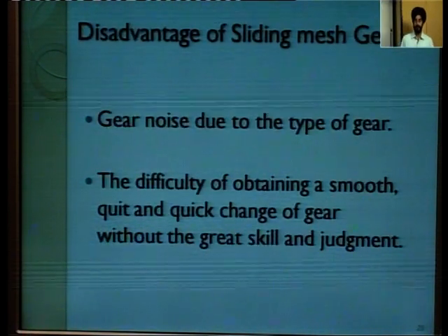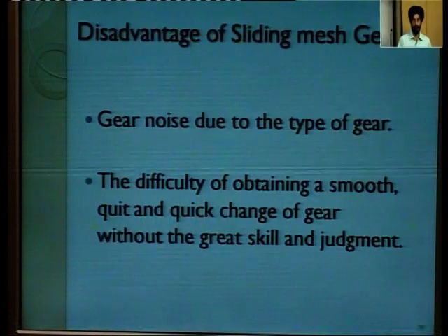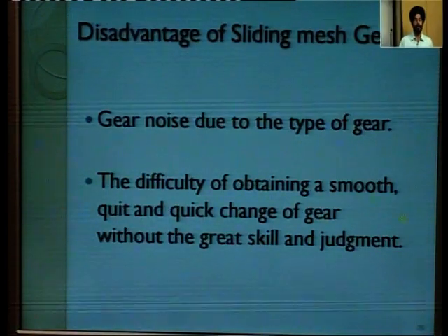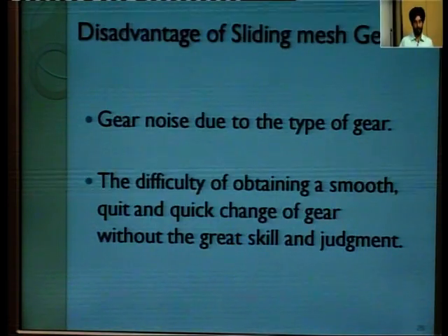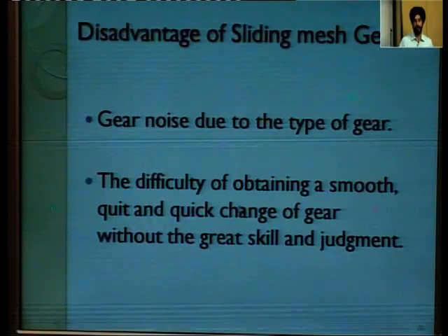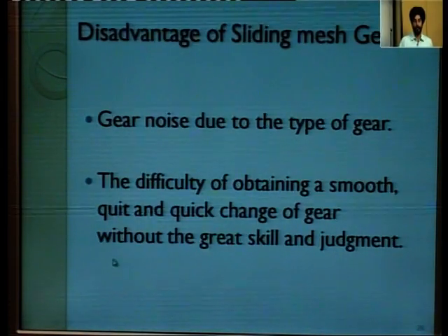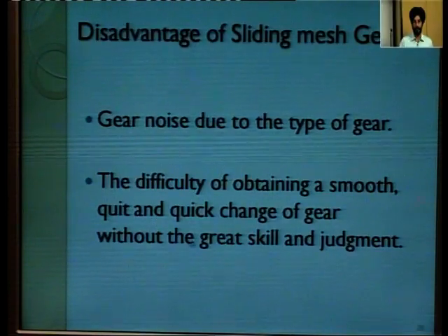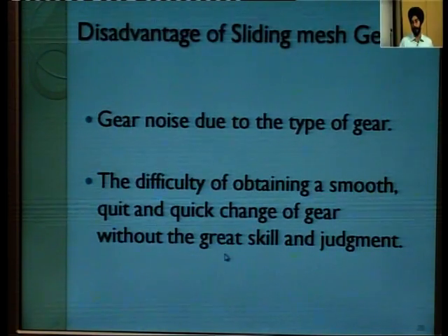What are the disadvantages of sliding mesh? Firstly, as we have used spur gears, these types of gears produce noise, and there is a difficulty of obtaining a smooth, quick change of gear without great skill and judgment.